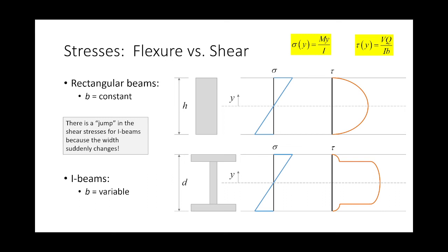Imagine that this book is a beam. I take the beam and I bend it. It doesn't have much flexural stiffness, it just goes, right? But if I were to take some glue and a lot of time and literally glue every single one of these pages together and press them together, and then do this, this would be a lot tougher. The reason is that the pages otherwise freely slide along one another.